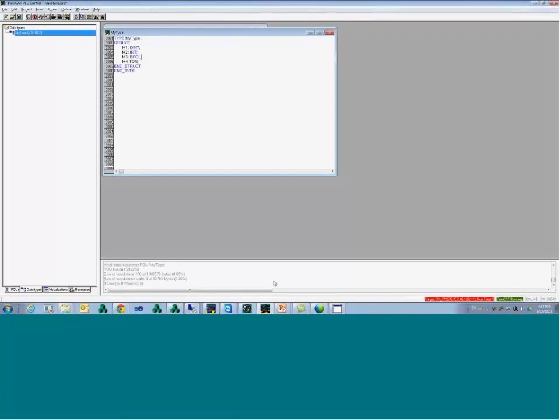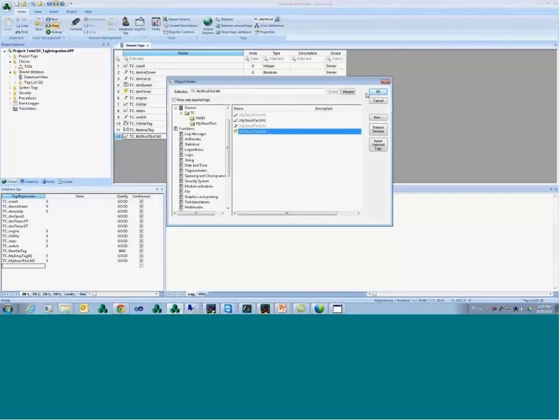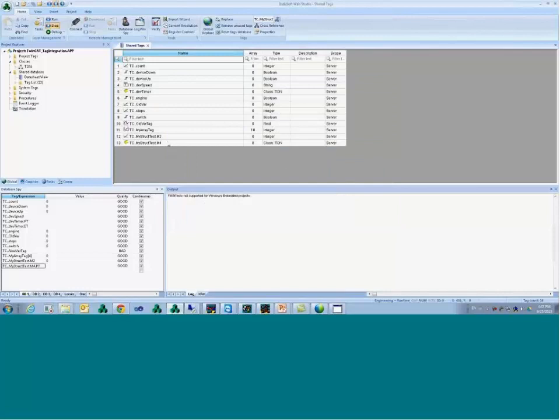But let's say that you're going to import the fourth member, that is a TON timer on delay. If I import that, that guy is going to come as, let's say I'm going to put PT here. I import this. Okay, so the whole M4 came because it's actually an existing class. So for the predefined types, like the timer on delay, timer off delay, we can use this option. We can import and create the class automatically.